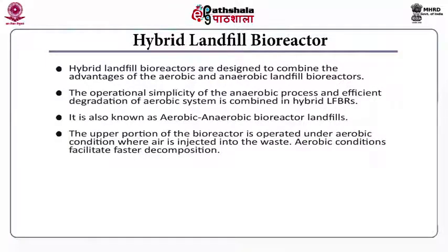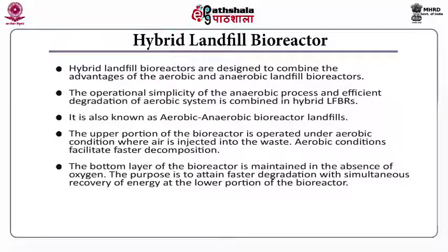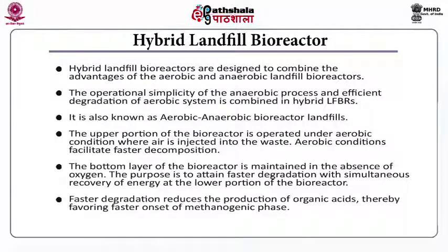The upper portion of the bioreactor will be generally operated in the aerobic condition since it is exposed to the outer atmosphere, where the air will also be injected into the waste. The aerobic condition will facilitate faster decomposition and the bottom layer of the bioreactor is maintained in the absence of oxygen. The purpose is to attain faster degradation with simultaneous recovery of energy at the lower portions of the bioreactor. Faster degradation also reduces the production of organic acids and also favors faster onset of methanogenic phase.